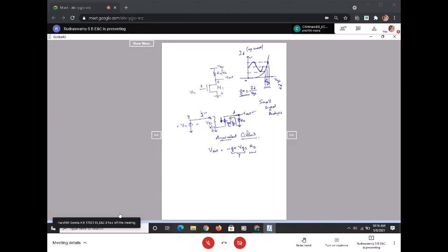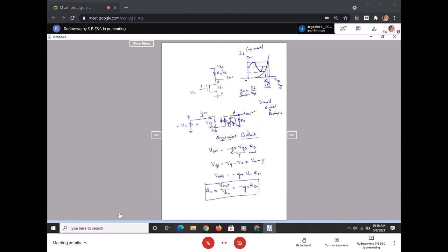That is the input. VGS is basically VG minus VS. VG is basically Vin, and VS is 0 because it is grounded. So I can say that V out equals minus GM times Vin into RD, or V out by Vin is equal to minus GM times RD. And V out by Vin is nothing but the gain form.